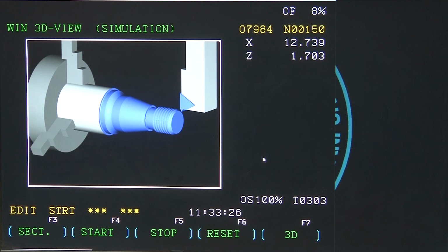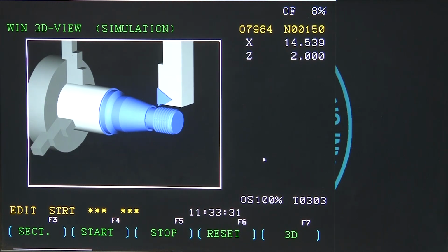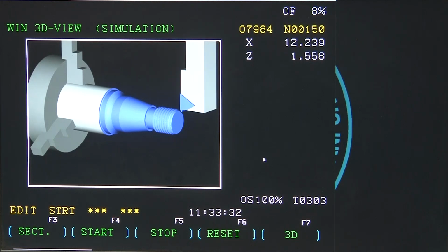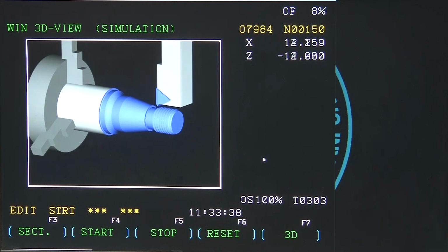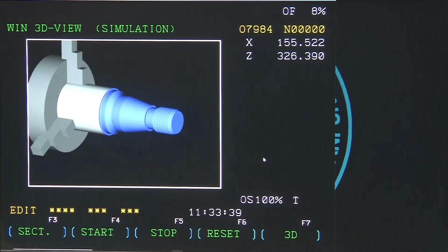Okay. So, there are a few passes; the final depth of the thread is obtained by a few passes of rough and finish turning finally. So, that is the whole program being executed, and you can see the entire part is being made according to the drawing, and this is the one that we have planned. So, this is how the part is made.